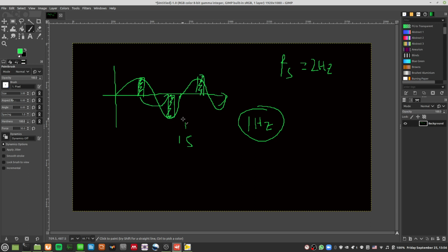So when we have such a case, you are able to at least make out that, okay, I roughly have a waveform there, and your bar chart is going to look like a sort of square wave. So it's going to go up and down like a square wave. So that's how your sampling will work. But you can see you need at least 2 times the frequency of the waveform in order to sample it properly. Anything less and it just doesn't quite work properly. You will not be able to distinguish a regular waveform from background noise. It's very hard to distinguish if your sampling frequency isn't high enough.